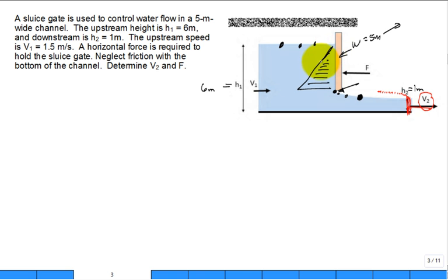How does it increase, but then do something like this to get back to, I don't know. It's too complicated. Let's leave it alone. It's because the fluid is accelerating in that vicinity. It's accelerating to scoot underneath the sluice gate. Let's leave that part of the problem alone by getting a larger control volume. And the other thing is, if you do cut the control volume up this way, it would need to be a force distribution that's acting on the water, pushing it that way. A lot of people show me the hypothesized force distribution on the gate. But we're interested in things that are acting on our control volume, which would be the water. Okay, so let's not cut there.